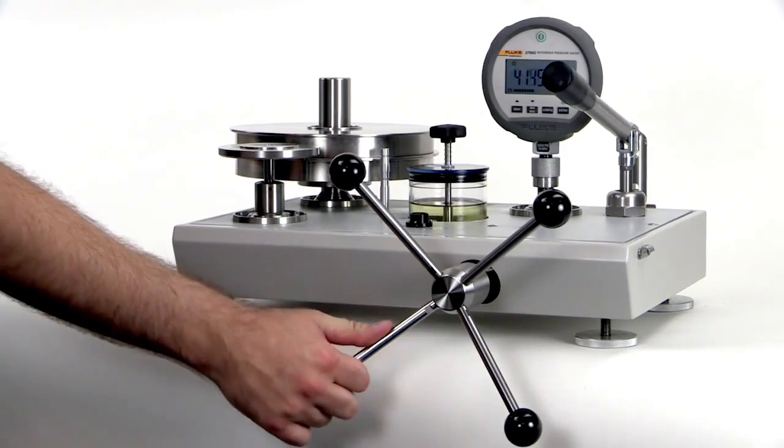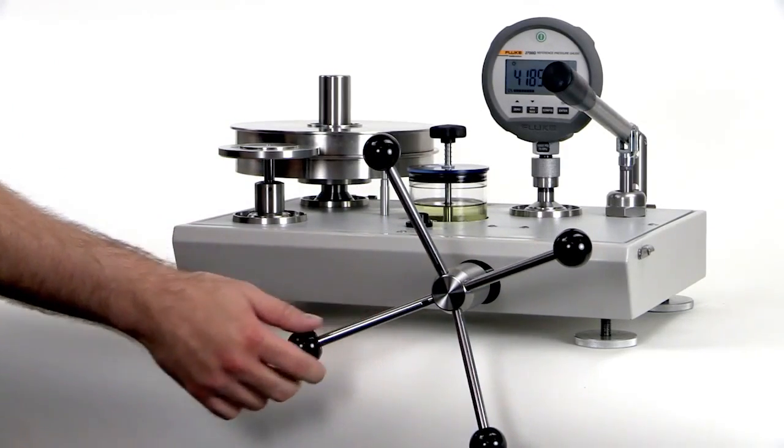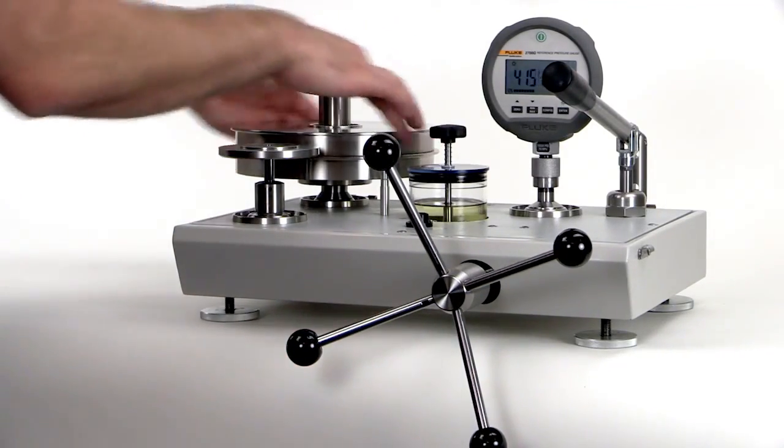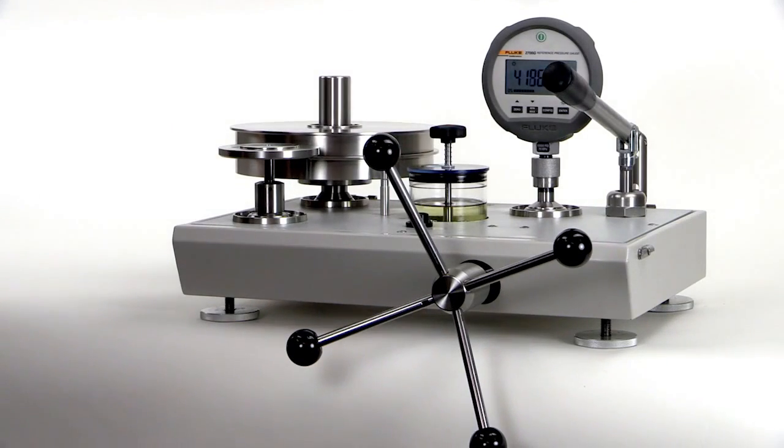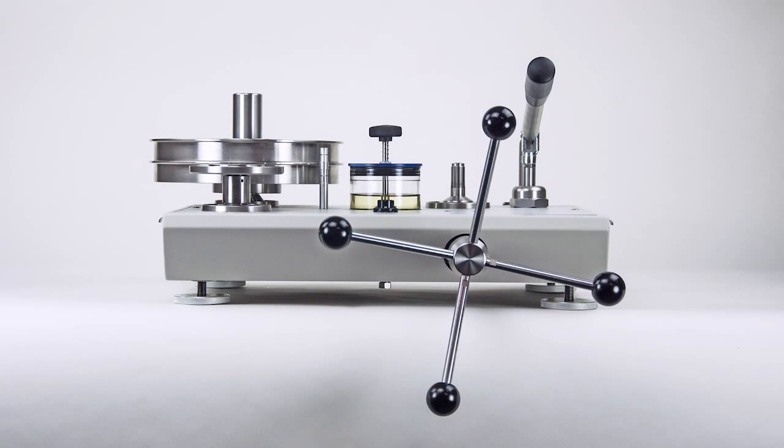At the time of manufacture, the amount of mass required to generate a given pressure at the customer's gravity is calculated. The masses are then trimmed to this value. Without this trimming, the user has to do some level of calculation. The concept of just adding up the pressures on the masses is completely destroyed. Therefore, Fluke Calibration performs this trimming at no additional cost to the customer.